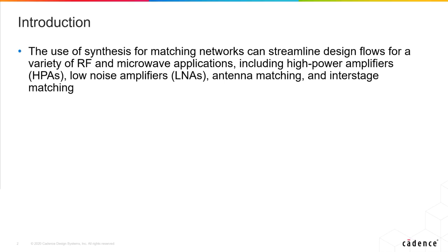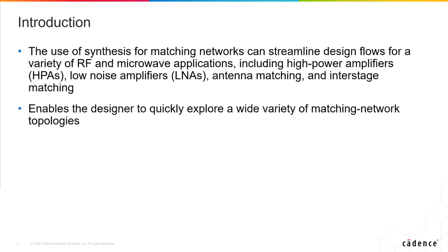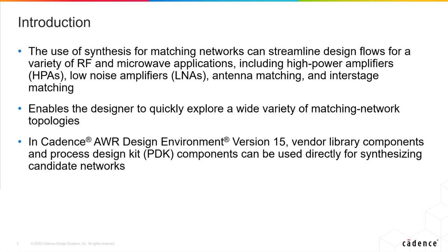It can be used for a wide variety of RF and microwave applications, including high power amplifiers, LNAs, conjugate matching problems, whether they be broadband or multiband problems. We have an example of a multiband antenna match we'll be using in a few minutes, and also an interstage matching where you've got complex impedances on both sides. So all of those problems can be challenging and time-consuming, and synthesis can help streamline those processes for you and enable you to quickly explore a wide variety of candidate matching network topologies.